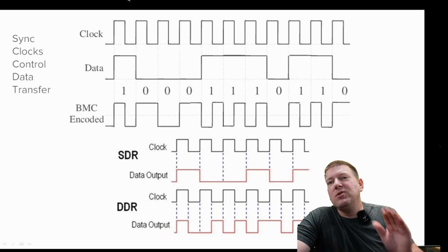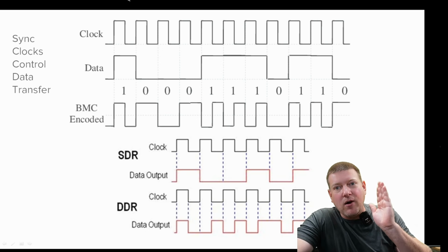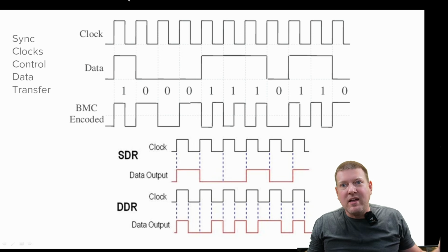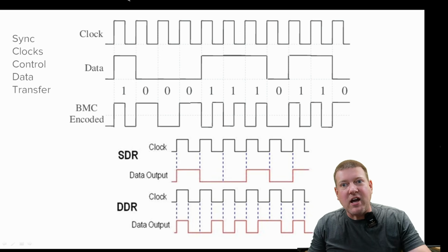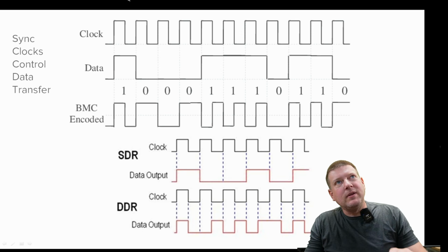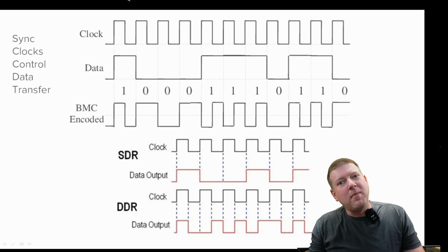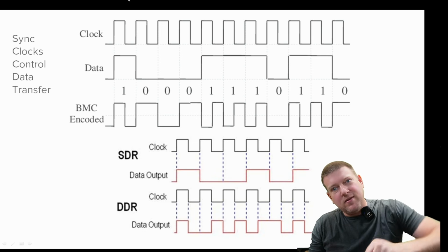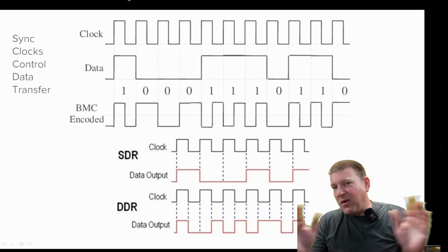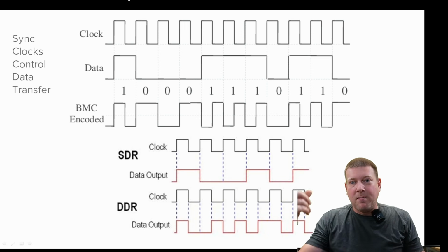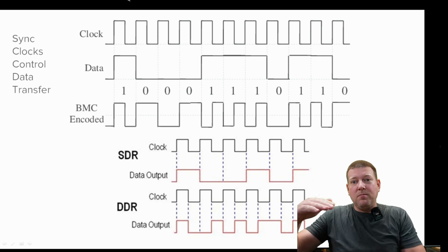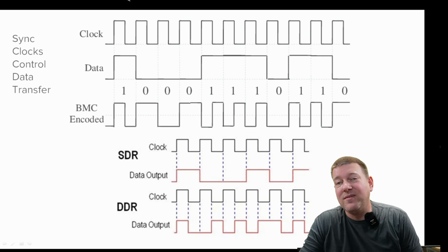And then over the next 3 clock pulses here, notice it says, that's a 1, that's a 1, that's a 1. So it uses the clock pulses to figure out at that second or that millisecond, what am I? Do I have voltage or do I not? But as we're going to talk about later, it's not always the case, because some of them will drive the pulse low on the clock, okay? So don't always think that a binary is a positive value, because it could be a negative value, or it could be both.